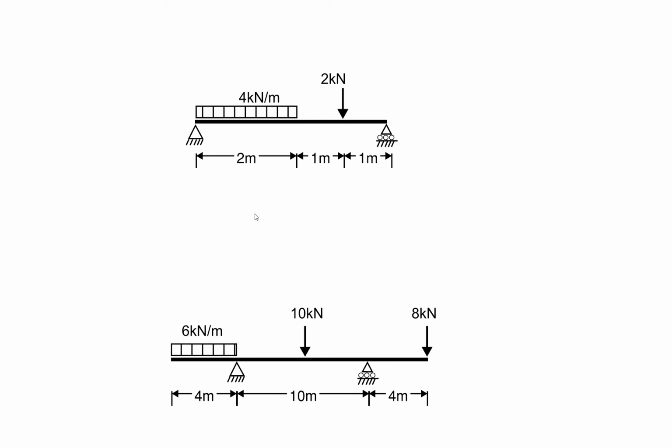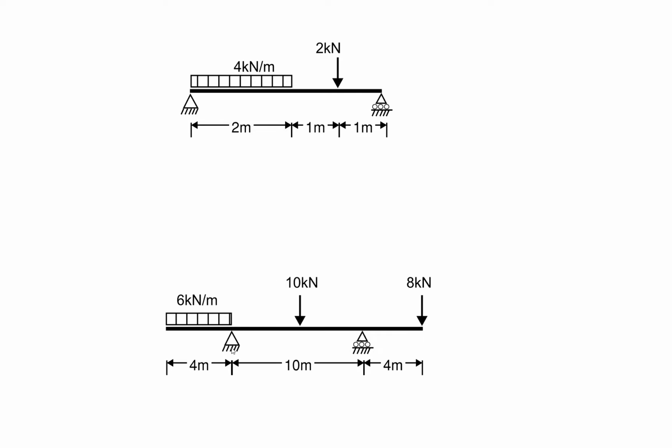Okay, again, let's have a look at some examples to see how quickly you can get the internal force diagrams and reactions without using software. I'm showing these two examples right here. One of them does not need the equilibrium method to get the reactions. You can use the graph method to draw your bending moment diagrams first, and then based on your bending moment diagram, you can derive your reactions quickly. So this is the case of what I'm talking about.